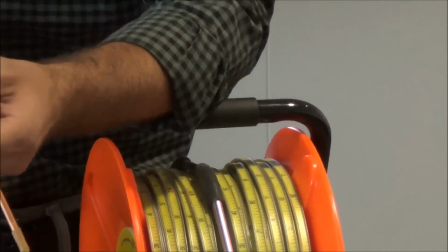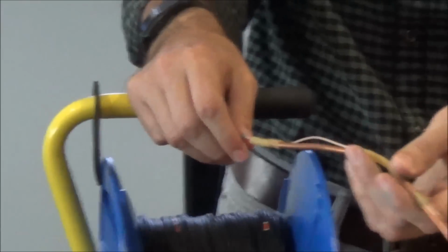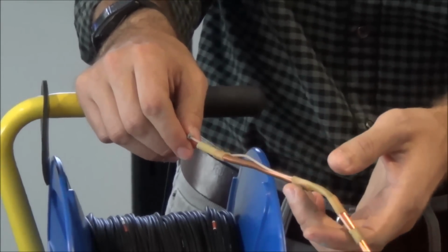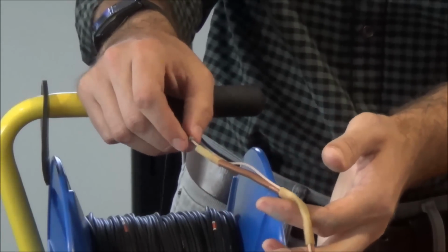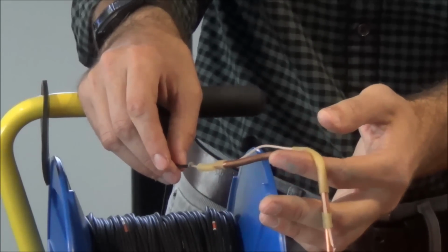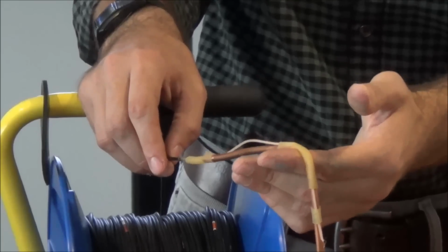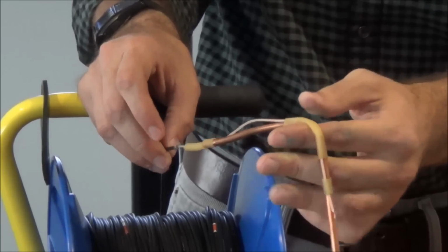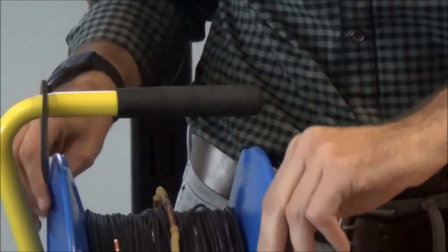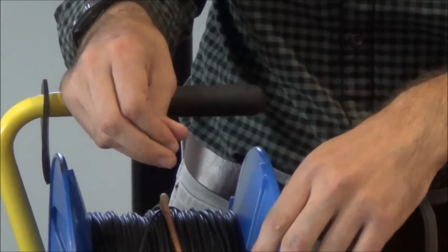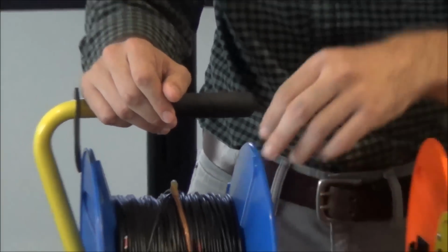Now the advantage of these weights over these heavier, larger diameter weights here is that we string them to slip off very easily. So if you get caught when you're down the well, all you have to do is pull and the weights will slip off the line and you won't have to cut your line. So it's kind of our motto here: it's better to lose weights than line. It's expensive to replace the line, but the weights are relatively inexpensive and they just settle down to the bottom of the well and don't cause an issue.